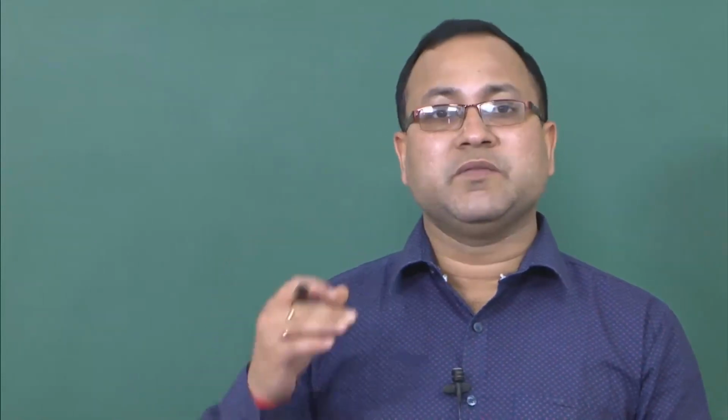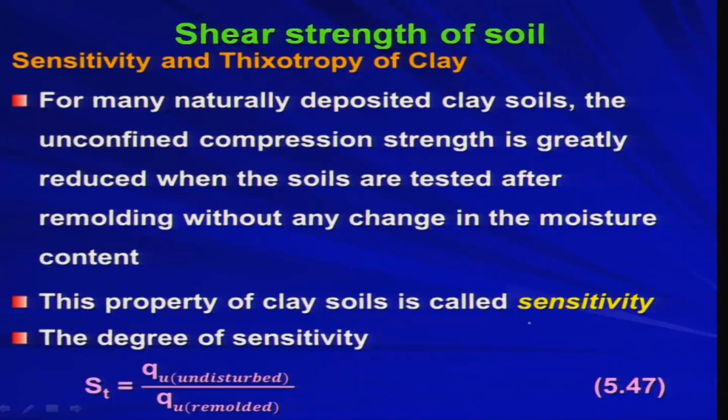If the soil is very sensitive, then you should be very careful, because it will cause significant variation in the shear strength parameters. You must take enough care when you are performing the test. So, this property of clay soil is called sensitivity. If I say my clay soil is very sensitive, then you have to take the utmost care.